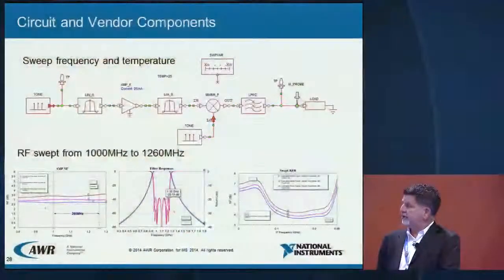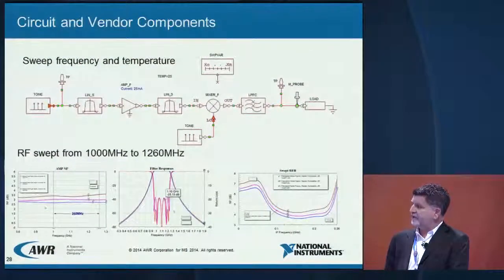So the steps were ideal, circuit-based model, commercial off-the-shelf component, getting closer to reality in our design. The next step is that we can do an analysis. Here we're doing frequency versus noise figure over temperature. A specific bandwidth has been defined. Each color indicates a different temperature, the characteristics of the filter that we're using.